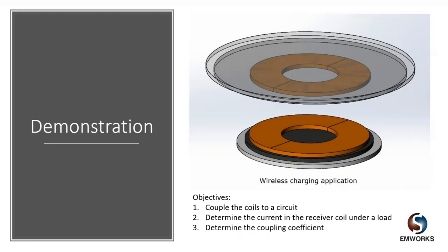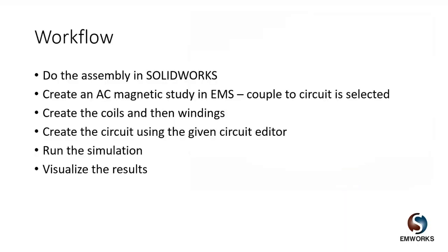Before I jump into SOLIDWORKS, let me just briefly walk you through the workflow that one needs to adopt to enable circuit simulation inside EMS. And I'll be going over this workflow at the end of this demonstration as well. So the first step is really to create your model in SOLIDWORKS, which is a 3D CAD software that you may be familiar with.